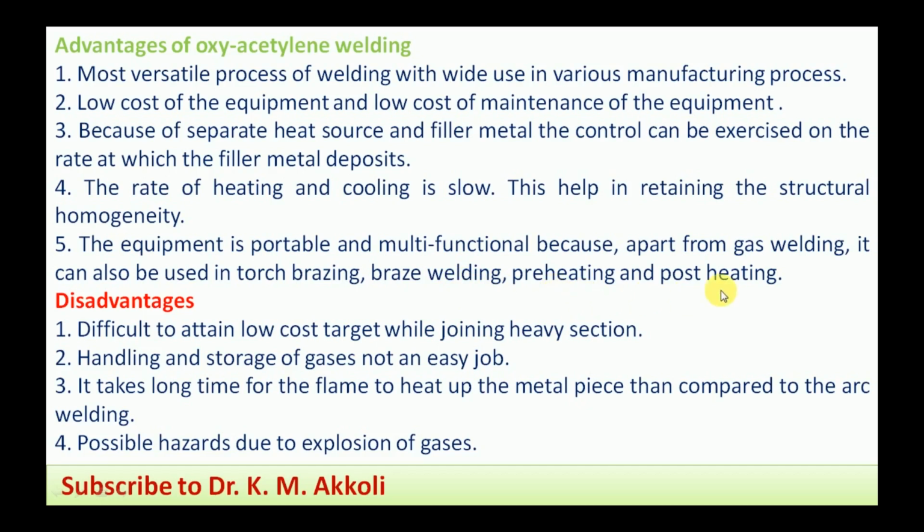Pre-heating and post-heating are other uses. Initially, to carry out any other operation on the metal, it may be required to pre-heat it, and we use the flame of the oxy-acetylene gases for that. Then post-heating, after the manufacturing of a component, if it is required to heat, we use it for post-heating also. The other application is metal cutting. Metal cutting also we carry out by using gas welding.